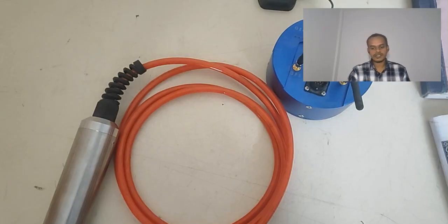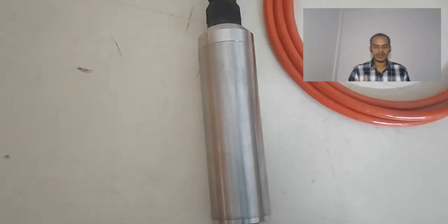And this particular station, the geophone or the sensor, has a 3-component sensing capability. So this can gather the information, or it can receive the information and show you from which side the wave has arrived. Is it from north-south or east-west, or from the vertical direction? In the coming videos I will show you the particle motion which is recorded by a sensor, that you can see in the graph. Now we'll go more deeply into this sensor.